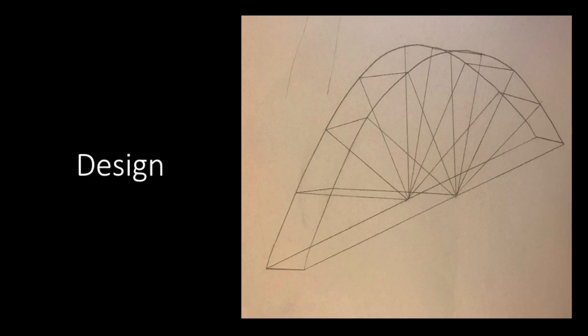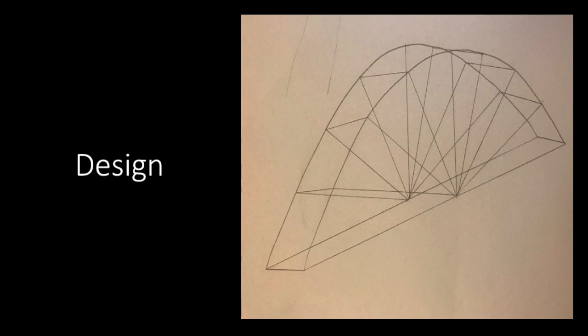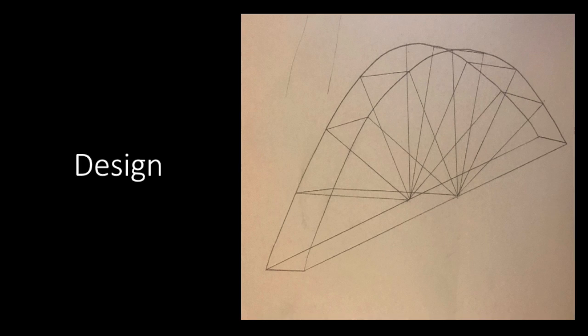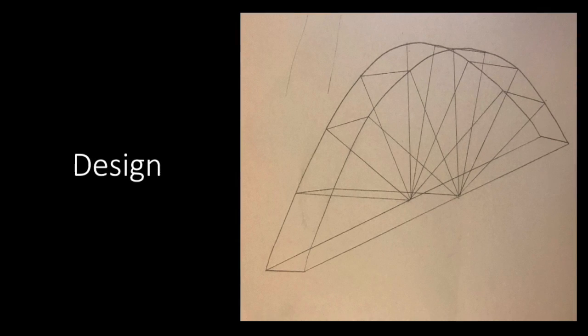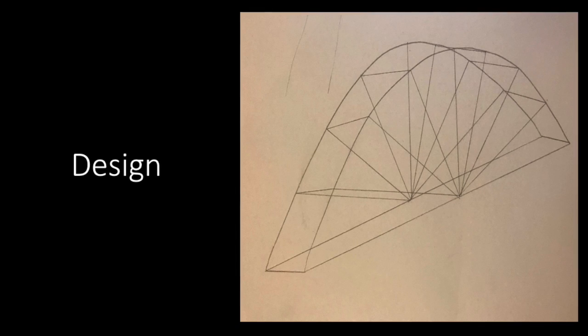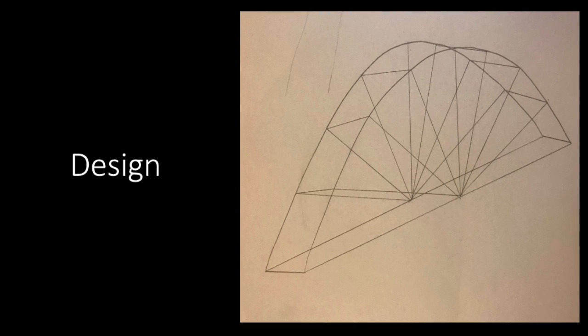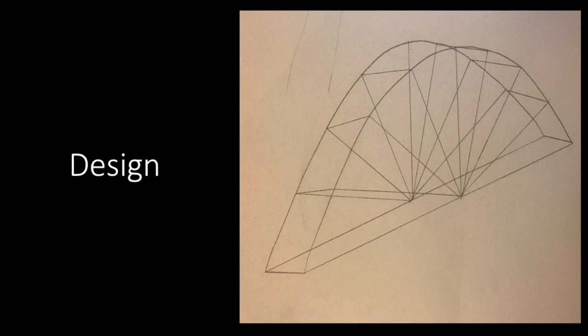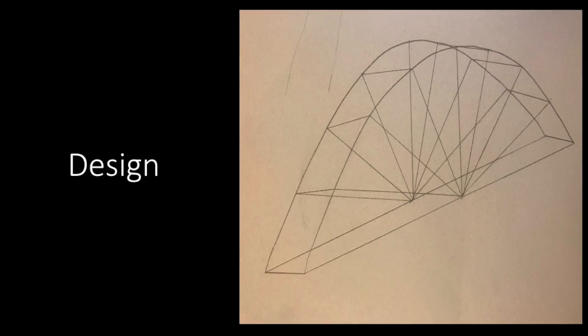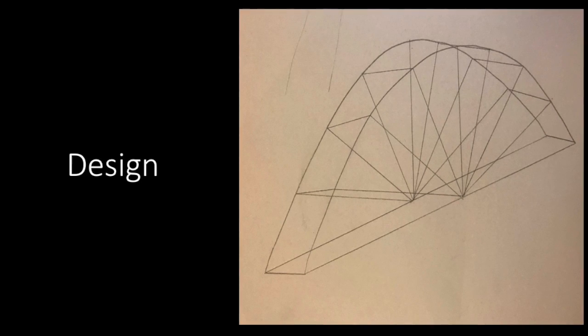For the design, specific structure is needed to strengthen the bridge to carry a greater load. If the beam bridge design is chosen, our bridge would be a single beam model and it could not carry a large load, meaning the beam bridge is excluded. The cable-stayed bridge and suspension bridge would be better utilised across longer spans, which is not appropriate for our bridge design, as the spaghetti bridge constructed would be approximately 400 mm long and 80 mm wide.